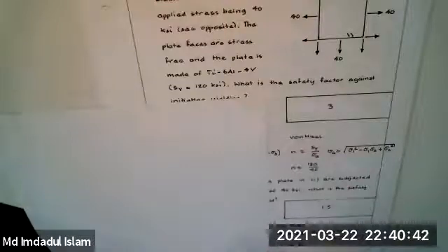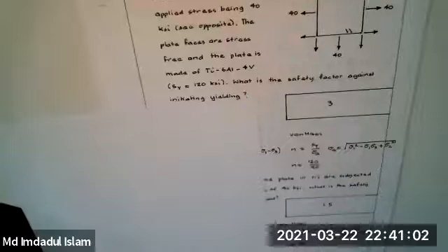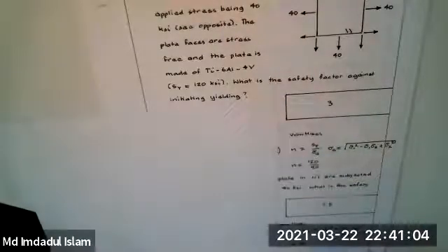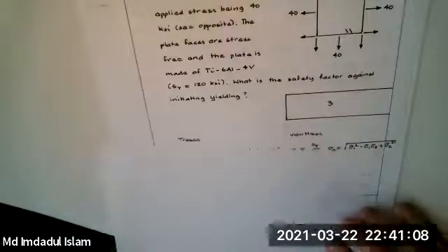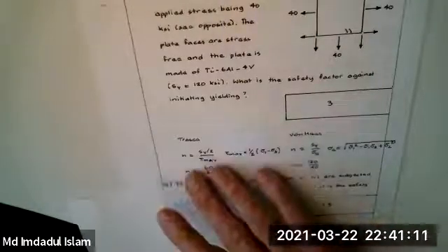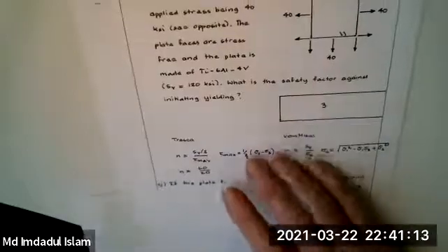You have these different sums. These 2 are equal, so it's 0, but this is going to be 40 minus minus 40, which is 80 squared. Minus 40, minus 40, minus 80 squared. So 2 times 80 squared. Divide by 2 is 80 squared. So sigma is 80. 80 divided by 120 is 1.5. You get the same answer. But for future reference in a final, for example, if you're asked to get safety factors against yielding, you can use either of these. It's what I said in class.